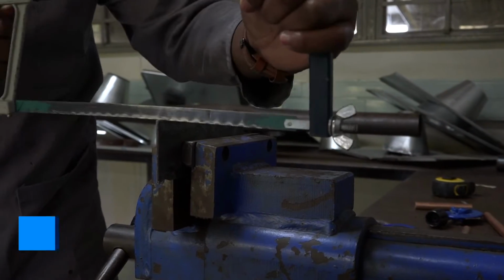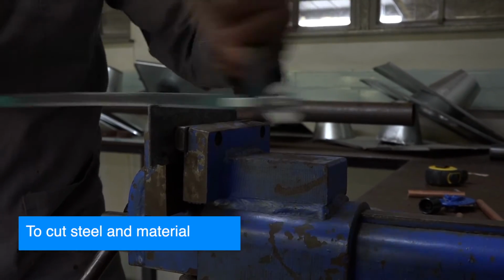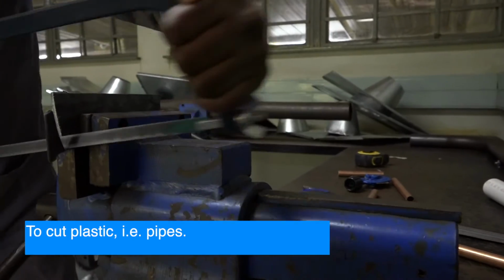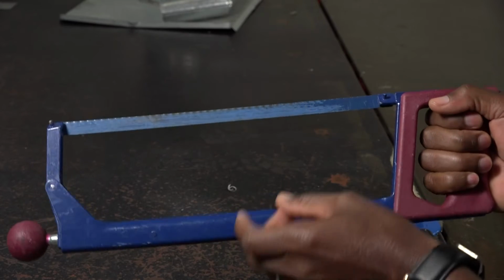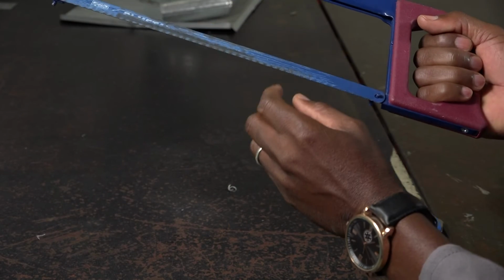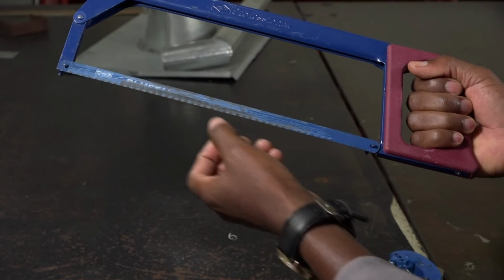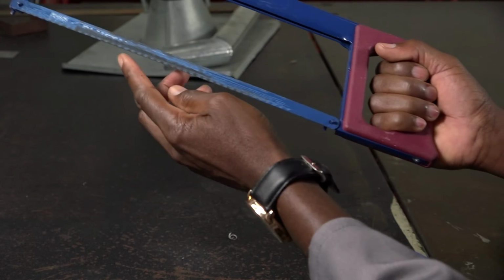The hacksaw is basically used to cut pipes and flat sheet in various measurements. The blade itself is the one doing the cutting work. But something that you should remember here is that the hacksaw blade has teeth. These teeth must always face in front. You have to make sure that it's always facing in front, as you see them here.